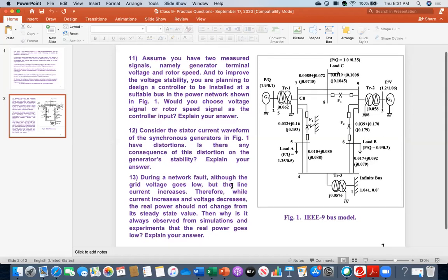Yeah, I think it will cause some harmonics. Exactly. So distortion is again nothing but the harmonics, right? Yeah. Therefore, if you have distortion here, you have to apply the Fourier technique, Fourier series, to decompose and find the useful component, which is the fundamental frequency component, and then the rest of the harmonic components. So if you use a frequency analyzer here, you can distinguish between the fundamental and the higher frequencies, and those higher frequencies will have an impact.